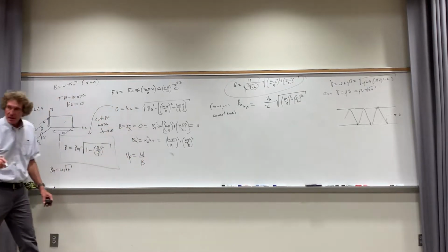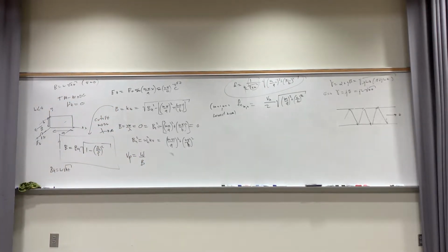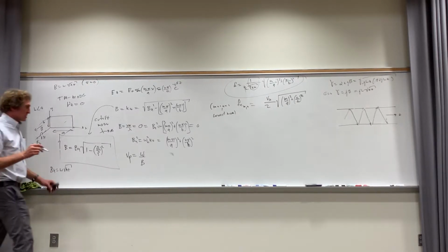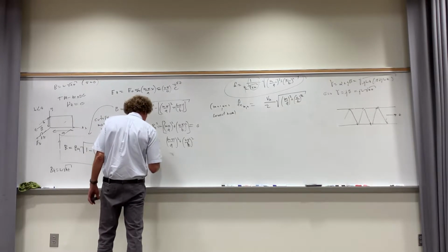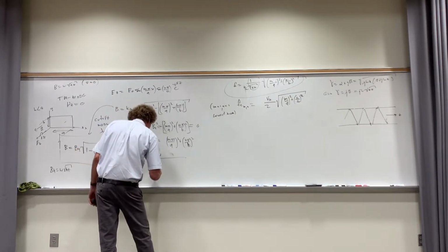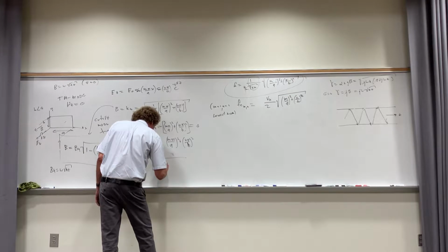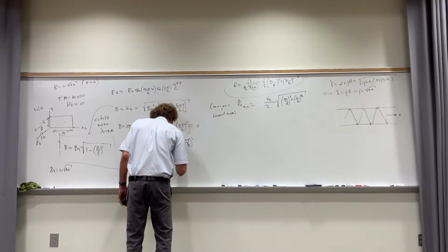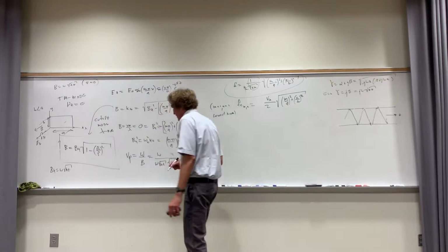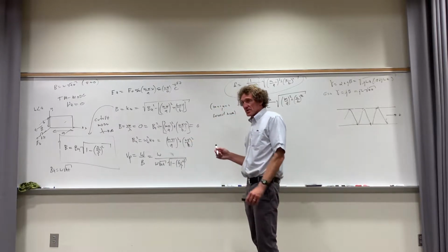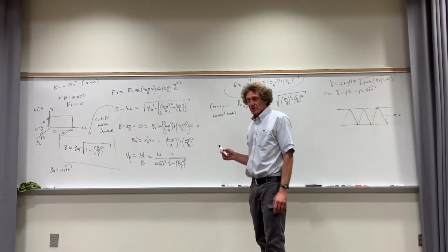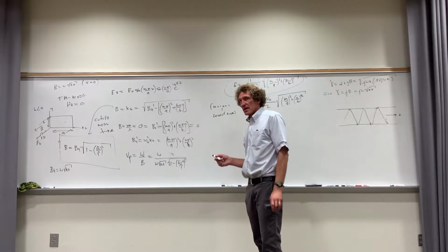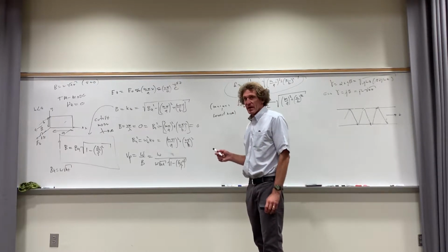Keep that in mind. That's the definition of phase velocity, and it comes from the argument of a cosine, but I'm not going to do that part yet. So if you look at this, it's omega divided by beta. Well, beta unguided is omega times square root of mu epsilon, then times the square root of 1 minus FC over F squared. Remember, that's phase velocity. Do you all see this, class? This is something that's going to come up again and again. I will ask phase velocity, velocity of energy, wavelength, things like this.